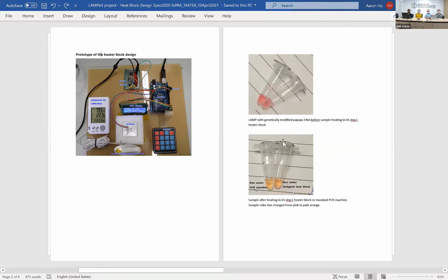So the next question is, how do we actually build that hardware, which includes programming the microcomputer from a computer, heating, and then detecting the temperature, feeding the signal back to the board, and then analyzing the temperature to see if it actually reaches the target number, and then keeping it constant by looping the signal continuously. So that's basically what it is.